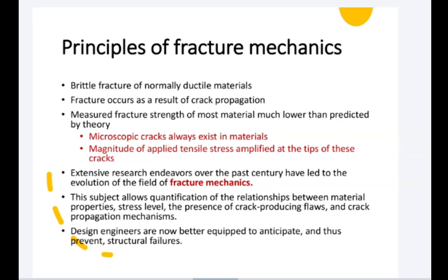Now cracks come from where? All the materials, whatever material you have, microscopic cracks are always present in the material, right? And when the cracks propagate, the material fractures. Now these cracks, when will they propagate? When we expose the material to the tensile stress, right? And the magnitude of the applied tensile stress is amplified at the tips of these cracks.